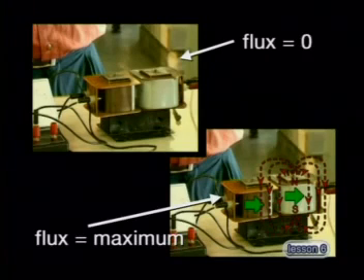Remember, a change of magnetic flux in a time interval is called the rate of change of magnetic flux. From Faraday's law, we know that the rate of change of magnetic flux cutting across the coil results in an induced EMF being applied across the coil. So Faraday's law explains why there is an EMF induced in the secondary coil when the switch was closed.